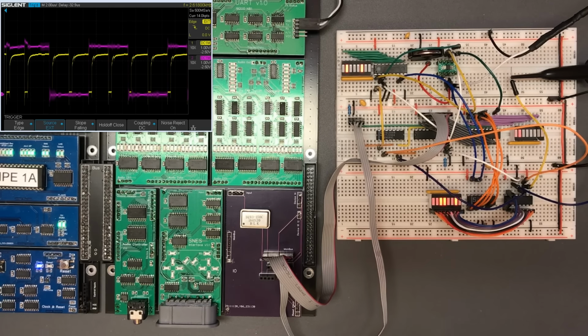Now, of course, what we want to see is a nice clean alternation between where the transition on the shift register from low to high is in the middle of where the data changes, but it's actually way over towards the start here. But that's just because our clock signal is very imbalanced, because our code has several cycles of work between the clock generation and then pulling the data in. And of course, that's the thing we're going to try and solve here.